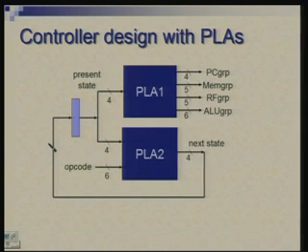One could have thought of this as a single combinational circuit with a total of 10 inputs and 24 outputs. That is possible, and it will be correct, but that will be much more complex than these 2 smaller PLAs put together.